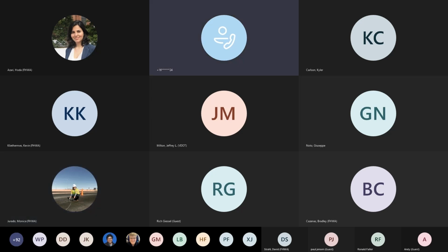Yeah, I didn't catch the first part, but the cedar has been used for bridges. It is an AASHTO-approved species that can be used without preservative treatment. I would say most people are using it in a northern environment where the decay potential is not so high. I know of some bridges in Alaska where they're using Alaska cedar. I don't know that it provides very good protection against insects of all types. Of course, bear damage is a concern for cedar. They scrape it all up. It's a very soft wood.